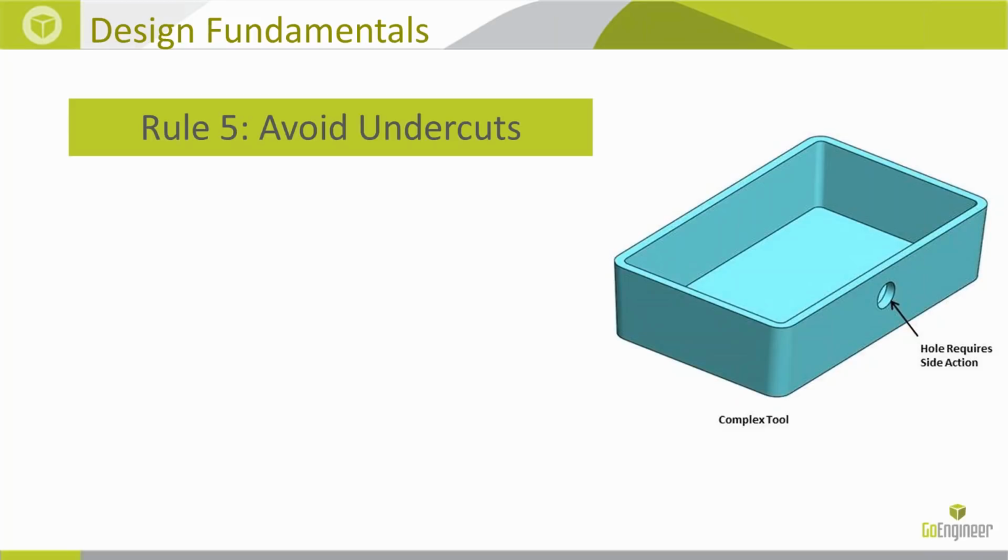So undercuts are basically features on the side of your part, and the side of your part is relative depending on where the parting line is. So that's just some plastics terminology there, but if you have a top and a bottom and a hole as shown in this illustration, what that means is when the part is molded and when you're injecting the molten material into this cavity, you now have to have a placeholder for that hole, that geometry, so that the material will flow around that shape. And for that to happen, you have to have some kind of side action or tooling.